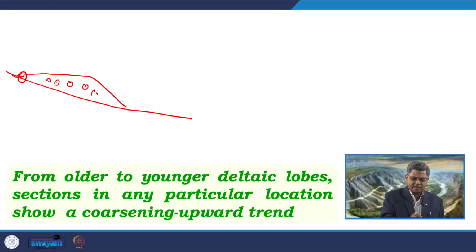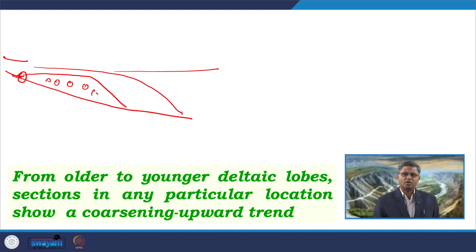Now, as the base level rises at this level, the river profile is also changing, so the energy is decreasing. Accordingly, the grains carried by the river will be distributed over here like this. In this grain size range, the coarser grains will be confined over here and the finer grains will be confined in this portion.